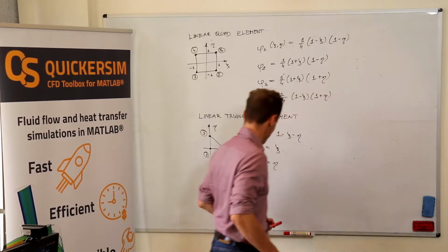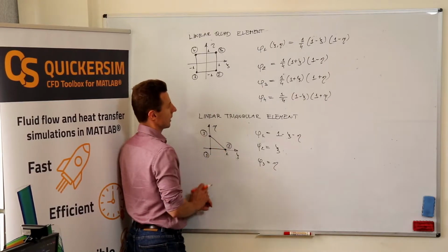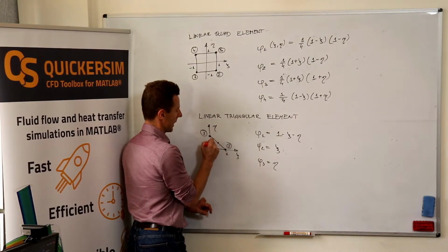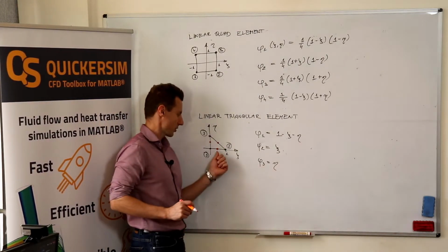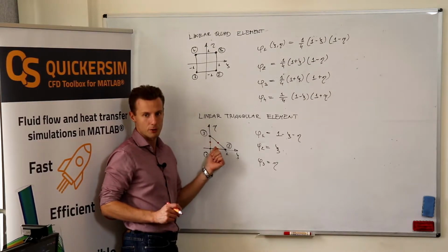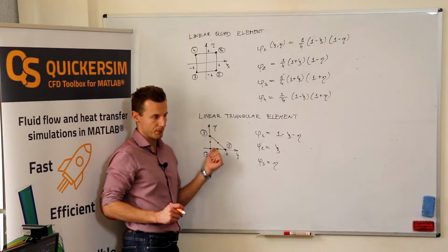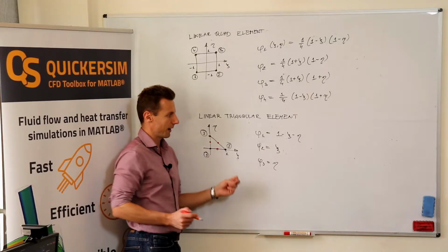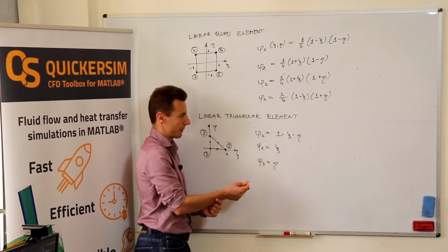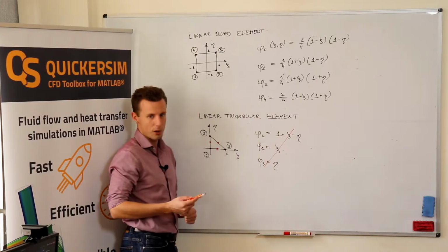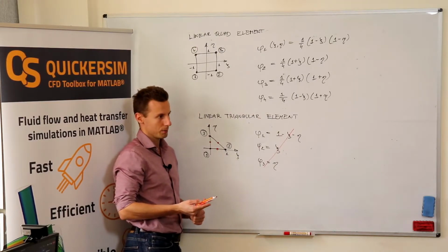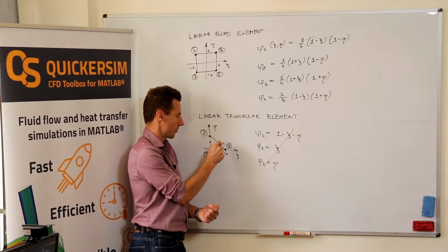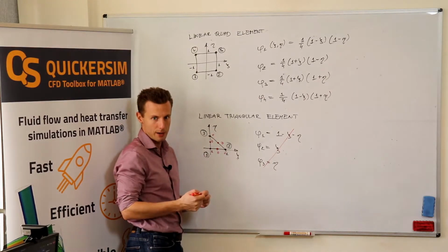So to develop higher order elements, we are additionally adding shape functions that are associated with additional nodes. Now, be aware that if you take the higher order triangular element, these shape functions do not hold anymore, because you need to derive new functions that will be 1 here, but 0, 0, 0, 0, 0 everywhere else.